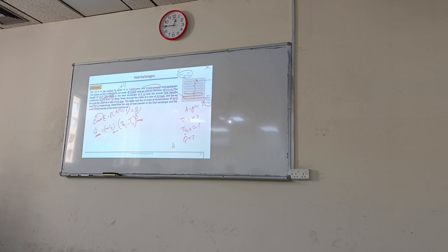Once you know Q, find T_co and T_ho using m cp delta T of the hot fluid and m cp delta T of the cold fluid.